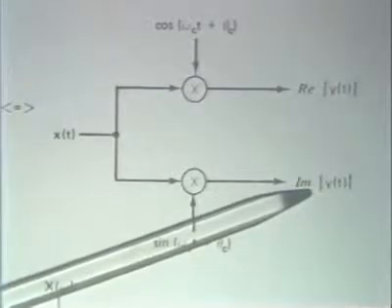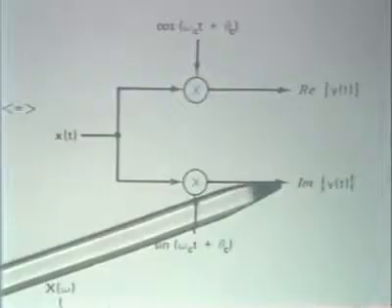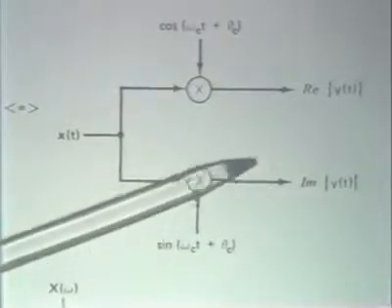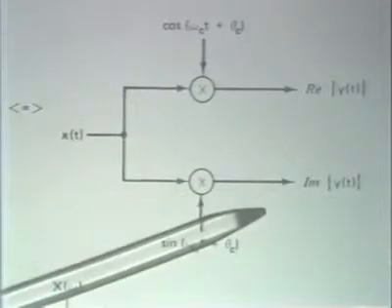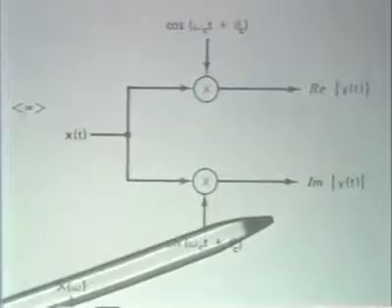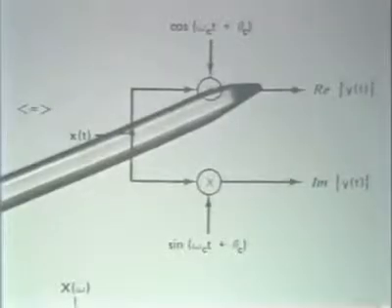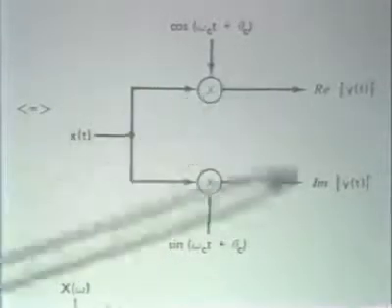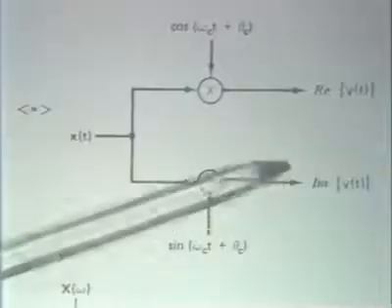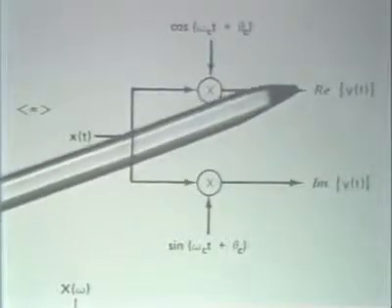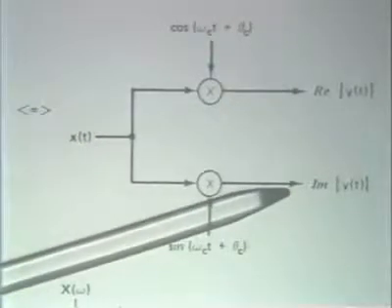And so, in effect, this is the complex signal if we just simply think of hanging a tag on here that says square root of -1 or j, and we appropriately combine complex signals following the rules of complex arithmetic. And indeed, that's exactly the way things are done in the real world. A complex signal is simply a set of two real signals.